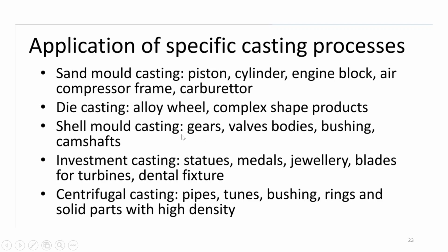Okay, so in case of shell mold casting, your shells will be providing precision to the gears, valve bodies, bushing and camshafts. Investment casting, about these castings we'll be studying in detail in the next chapters, but here we are just going through what the applications are, because you'll be asked questions based on these as well in this chapter. So some statues, medals, jewelries, blades for turbines, dental fixtures, all these can be made using investment casting.